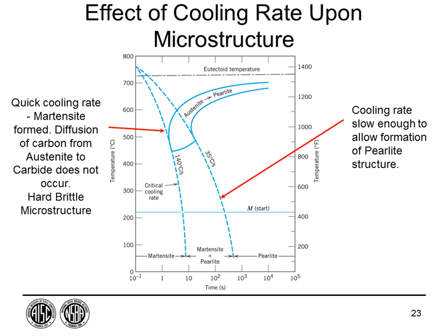So we have two options. If we want to just end up with our ferrite pearlite steel, we'll want to go on this side of the curve. If we want to form the martensite, we want to cool it quickly, and so we want to be on this side, a rapid cooling rate. And what's important is where these lines are that represent the start and end of the transformation. Higher alloys, higher carbon steels tend to move this to the right, which makes the steel easier to harden, which we'll see later on also means it makes it hard to weld.